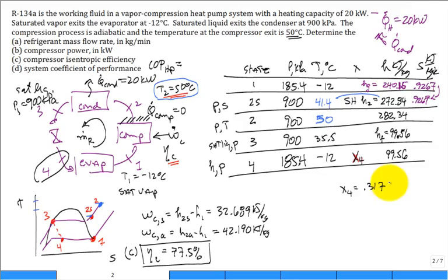Anyway, let's press forward. I think we can calculate the refrigerant mass flow rate. We needed 20 kilowatts up here, so Q dot in the condenser is the mass flow rate of the refrigerant times H2 actual minus H3. We know H2, H3, and the Q dot. The only thing we don't know is the mass flow rate of refrigerant.